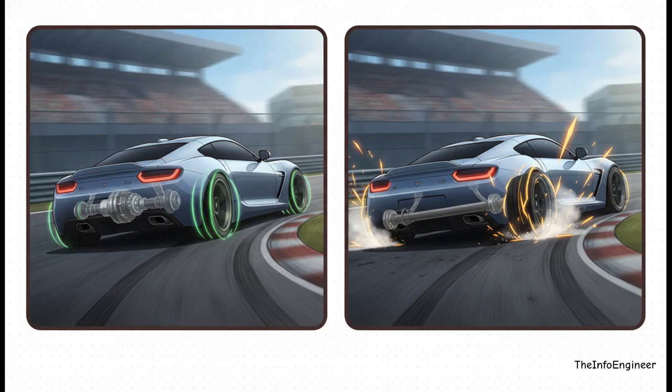It's awesome for drag racing or throwing a budget drift car sideways, but the downside? Daily drivability goes straight out the window. It totally prevents the wheels from turning at different speeds, so the car just violently skips, hops, and scrubs tires through corners, putting immense, terrible torsional strain on the axles.